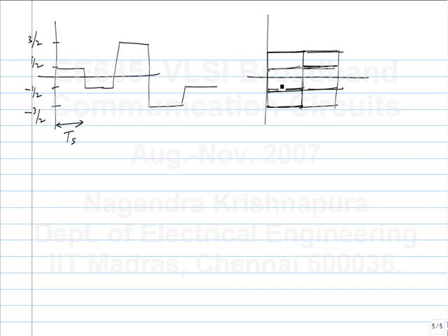Now let's say the same data was going through an RC filter. What would it look like? Yeah, there will be some rising exponential. So let's say the exponential does settle, but there is some rising part that is visible. Let's say it's something like this. So there can be a transition from this, similarly from this to this. So it's a collection of all possible bit transitions, and in this case, I said it fully settles, so I conveniently bypass the effect of ISI. I mean, there is some ISI, but not too much of it.